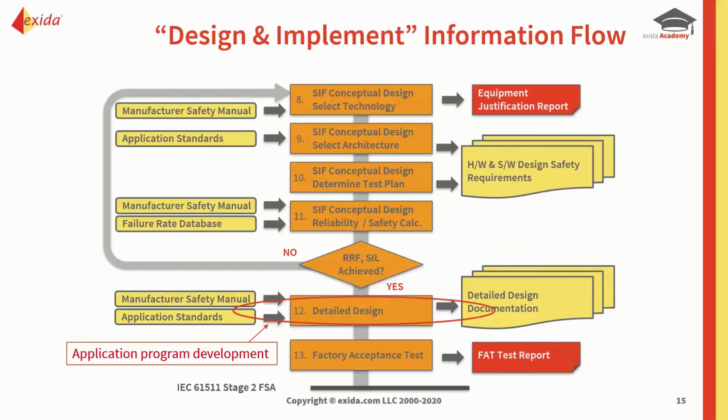So there might be restrictions, there may be some configuration information in there, especially if we want to utilize diagnostics, and there might be some application-specific information in there that we need to know. So if we don't have the manufacturer's safety manual, then we could end up, again, introducing systematic issues because we haven't fully understood what we need to do from the application program side of things.